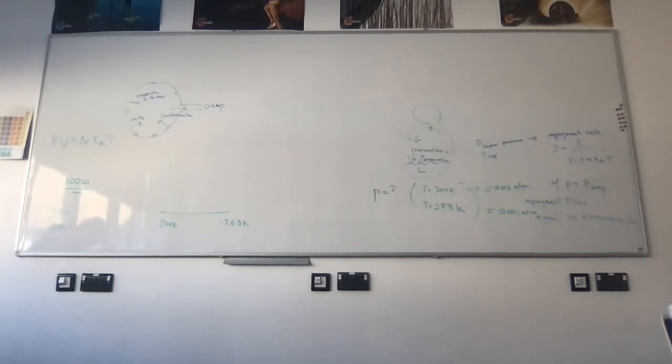Okay, so at this 3.3 value, there's a huge difference between them. Some of them are already at 10 to the minus 3. So 7 and 8. Is that right? Yeah, 7 and 8 here are already 10 to the minus 3 torr. Okay, a torr is more or less like a millibar, so 0.7 of a millibar. So that's extremely high vapor pressure. Well, it's much lower than an atmosphere. It's about 1/1,000 of an atmosphere, but it's still very, very high with respect to the different regimes of vacuum, et cetera.